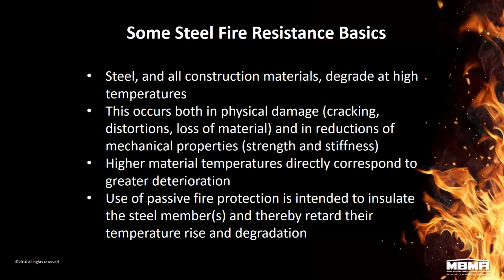Higher material temperatures are directly proportional to this deterioration, both physically and in terms of mechanical properties. Hence, your fire resistance and your fire protection is intended to slow, retard the increase in the temperature of the construction material and thereby to minimize or mitigate the deterioration of its mechanical properties and its physical damage.